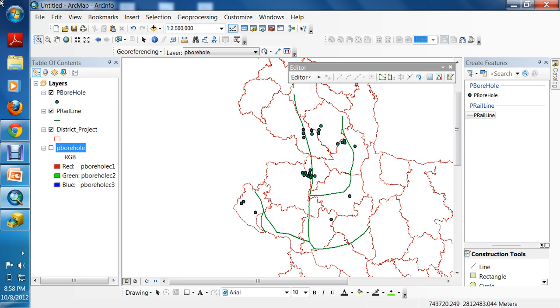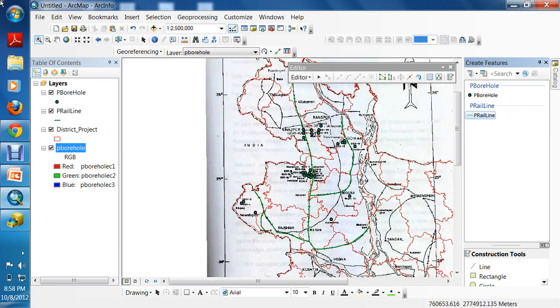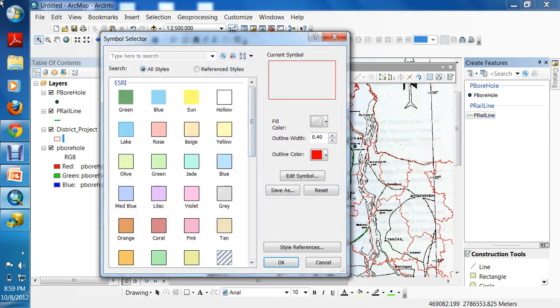So you can digitize maps combined from 2, 3 or 5 maps. For example, this map doesn't have any roadway connections, right? If you have a map with roads, then you can digitize and make that map projected with the same projection system, and you can add it here, and then you can digitize this map using another shapefile, road. If you create another shapefile, say river, then you can also digitize the river. According to your preference, whatever you want, you can do that.